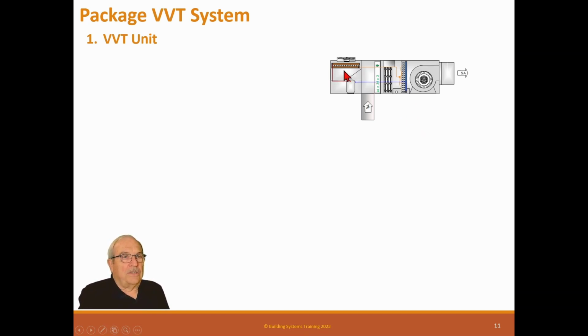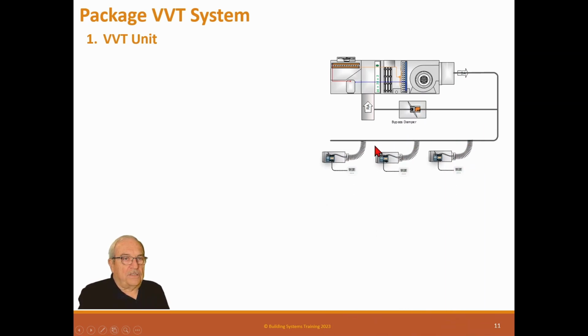And basically what it is, is a standard package air conditioning system with a supply duct system that puts VAV boxes in each space. Now, these are capable of using a full VAV box, just like the other systems, or else you can use these, which I call cheap boxes. They're a little round piece of duct with an elliptical damper in them, and they're really inexpensive. They're just a round piece of duct with a damper and an actuator, and a controller for the box on them. Much less than a standard VAV box, but it doesn't have a lot of sound attenuation because it's just a piece of duct, right? So it's no big deal.